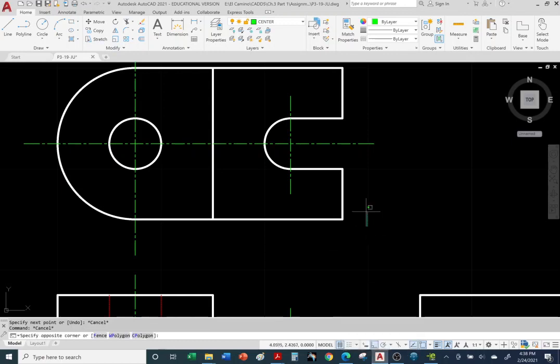By the way, if you were to create a center line, let me turn off ortho temporarily. If your center line looks like this, that is incorrect, right? It's supposed to be vertical. So if you drew your center line like that, that tells me, oh, this student forgot to turn on ortho and created a vertical line that's skewed. It's not a vertical line. So this is incorrect. So you would have to go back and fix it. I will take points off if your lines are not vertical or horizontal as they're supposed to be, right? So you would have to fix this.